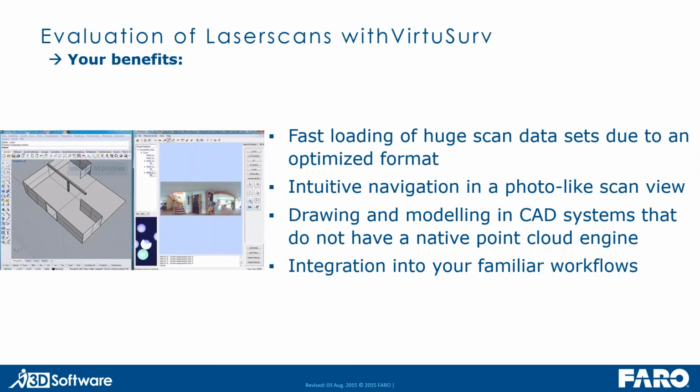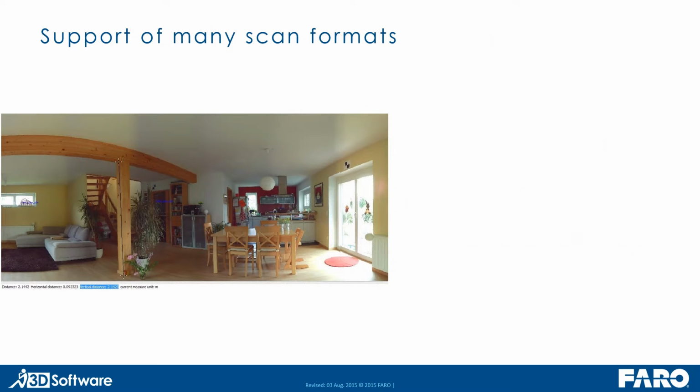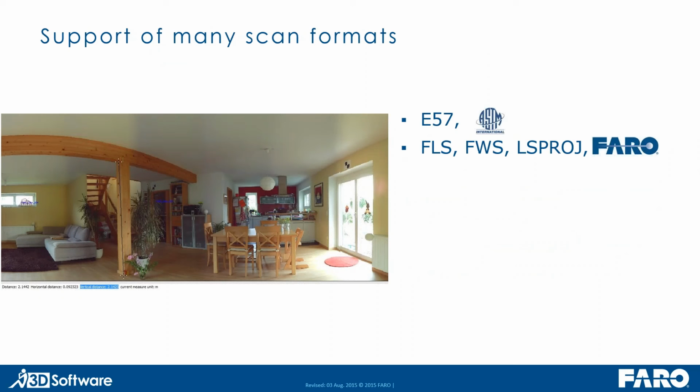So let's have a closer look. First, what type of scan data does VirtuSurv support? In VirtuSurv you can import the standard format E57. This way you can get scan data from almost any laser scanner into VirtuSurv. So you can get your Riegl data into VirtuSurv this way if you're a Riegl user.